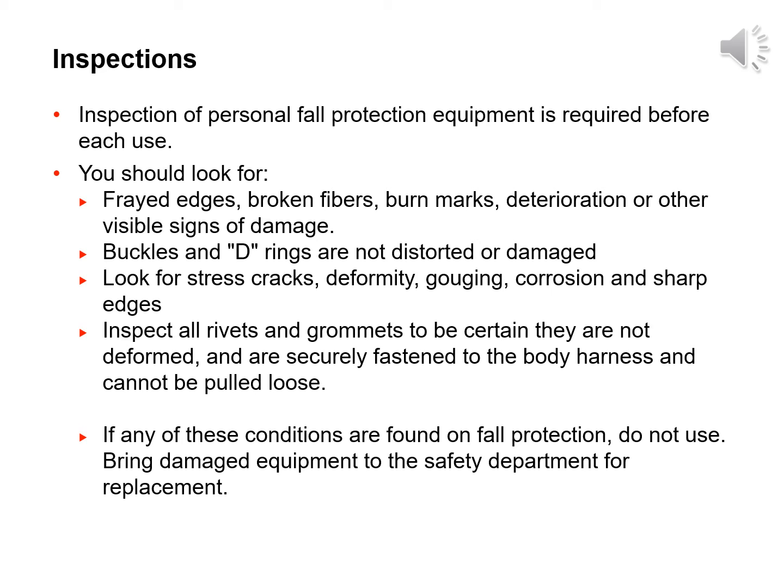If using a self-retracting lanyard or yo-yo, you must inspect the body of the mechanism for flaws to assure that all nuts, screws and rivets are installed and tight. Also check crimped ends or stitching for damage. Inspect the entire length of the self-retracting lanyard for any visible signs of defects. Test the locking mechanism by pulling sharply on the cable end to be sure it locks immediately and firmly.